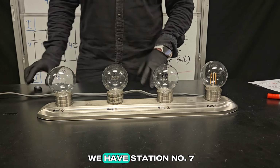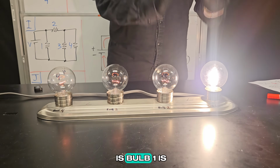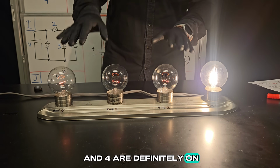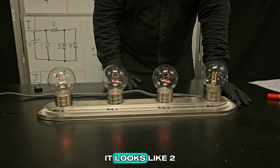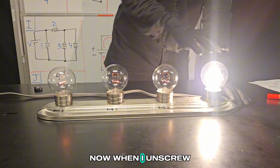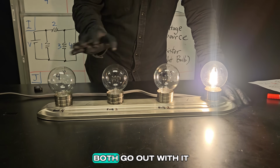All right, so here we have station number 7. Let's go ahead and turn it on. And what I notice is bulb 1 is significantly brighter, but bulbs 2, 3, and 4 are definitely on. They're just much dimmer. When I unscrew bulb number 1, it looks like 2, 3, and 4 are all still on. Now when I unscrew bulb number 2, bulbs 3 and 4 both go out with it.